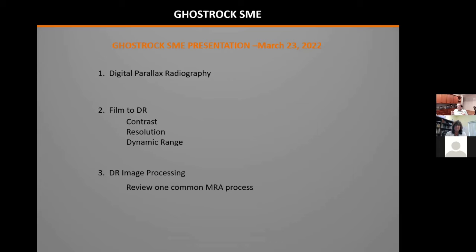The one thing I will comment on rotation, however, is that things that are out towards the tangent on your rotation, when you move it on a projection image, don't move as far when you rotate it. If it's towards the center of rotation, it's going to move a long way. So your measurements are more likely to be accurate the closer the indication is to the center of rotation on your projection image. When it gets out towards the tangent, it's not going to move as far. That movement, when you rotate things around circularly, is sinusoidal. So things towards the center of rotation will move further, and things on the outside will move less on your projected image. So I will comment on that.